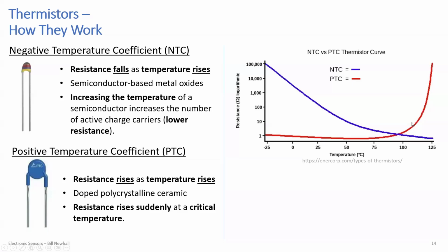At some very high temperature. Okay. So you wouldn't want to use a PTC thermistor as a temperature sensor in these ranges, because you're not changing much resistance over temperature, and it's going the wrong way for a PTC. And then if you look at 1 ohm, you cross 1 ohm here, you cross 1 ohm here, so you can't tell at 1 ohm what the temperature is. Is it somewhere over 75 C, or is it somewhere below 0 C? So mainly